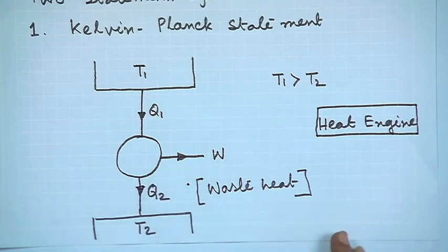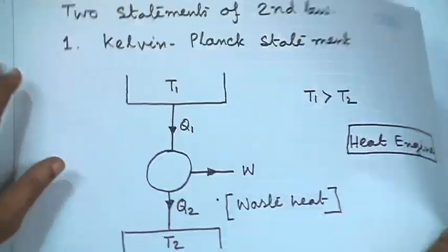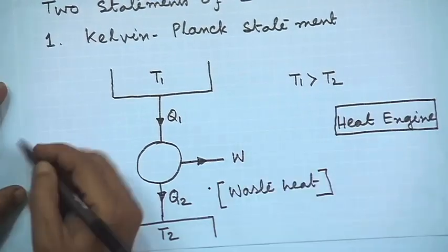And well, here again we can define some other thing. You see, the energy which we are getting from a high temperature source, for which we generally have to pay, is equal to Q1. Unfortunately, the whole of Q1 cannot be converted into W, the useful work which we desire. Only part of it can be converted to W. So, here we can define another thing which is the efficiency of the heat engine. So, let me define it.